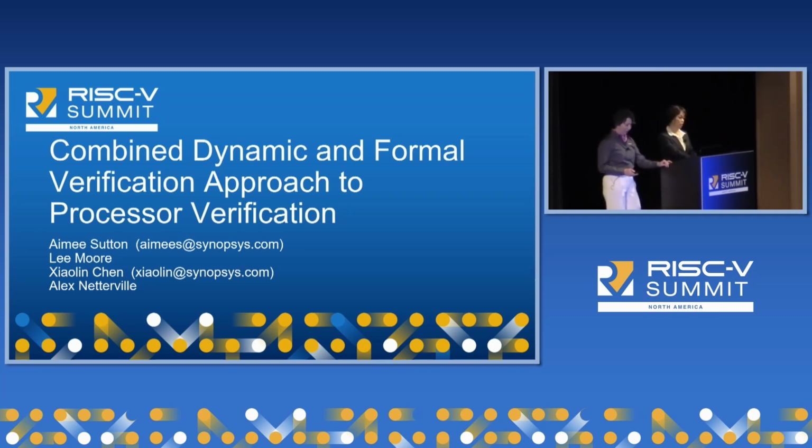And when I talk about formal technology, what comes to mind? Maybe not the same as you think. Some of the designers may be wondering what it is. What I'm referring to here is really formal property verification, where mathematical analysis is used to check whether the design satisfies the functional requirements, right? So formal is exhaustive, very efficient at exploring corner case scenarios, and very good at finding bugs, finding counterexamples, right?